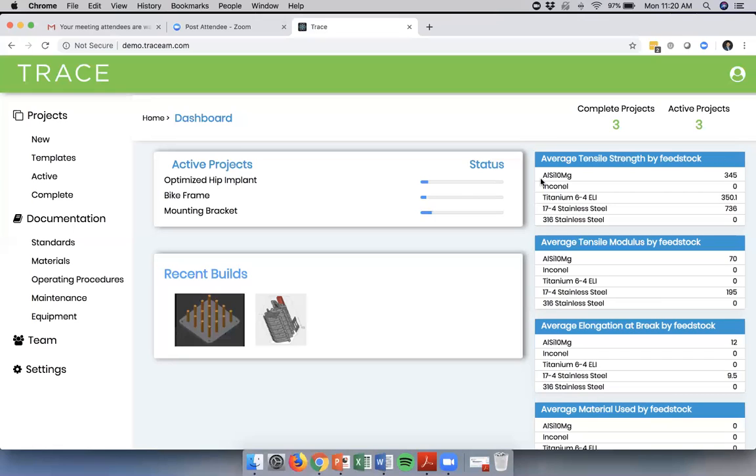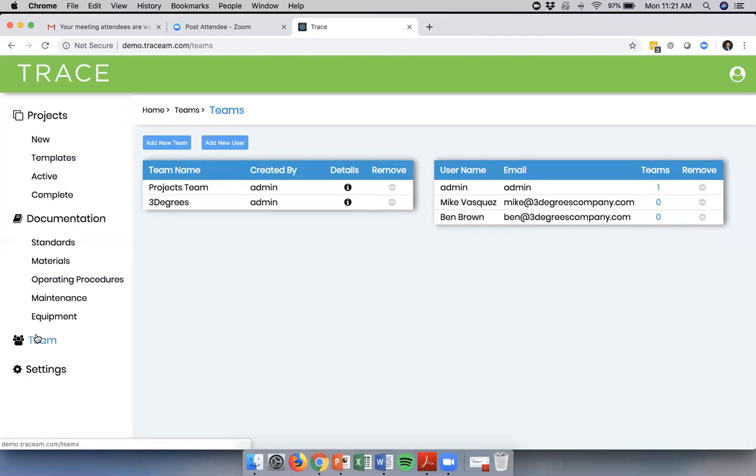the actual part, as well as tracing that back to tensile strength or whatever it would be. So automatically taking that ratio of laser power over scan spacing for some of the powder-based processes and implementing that here, so you can have an over time view of that process. So as we get into this, one thing I'll highlight first is the team function.